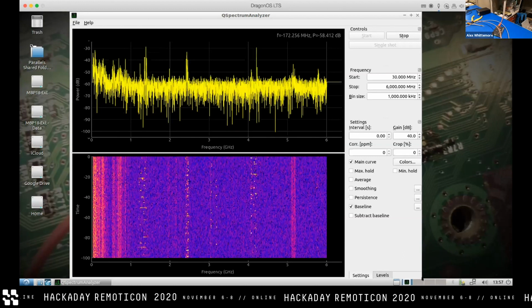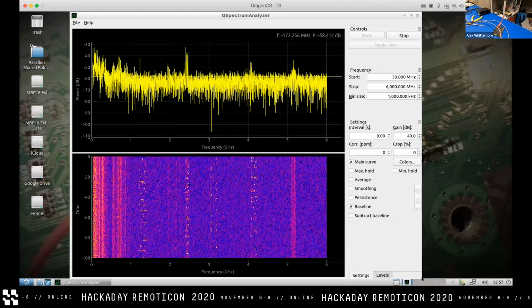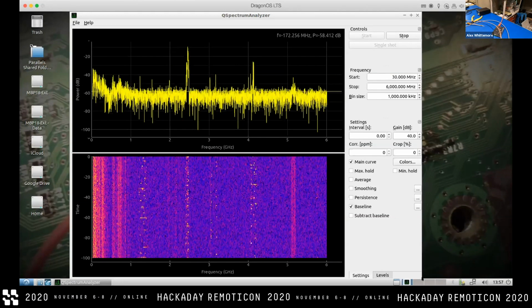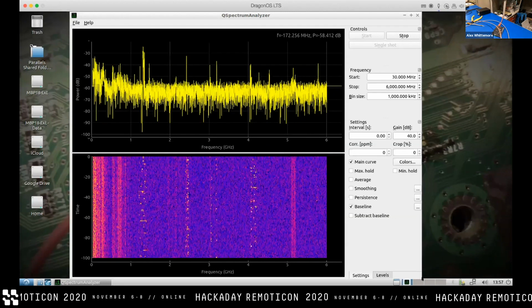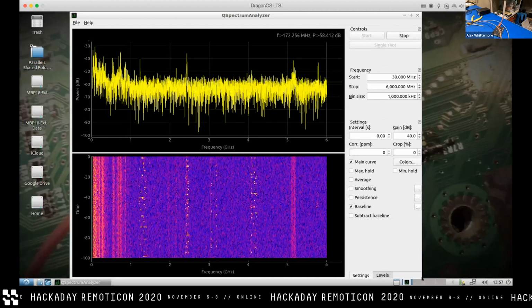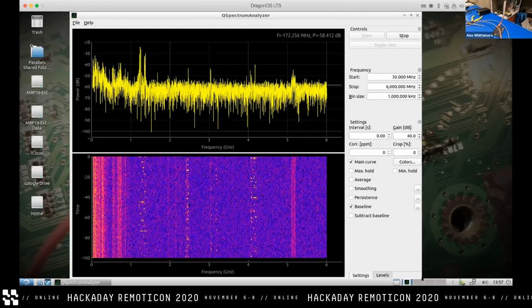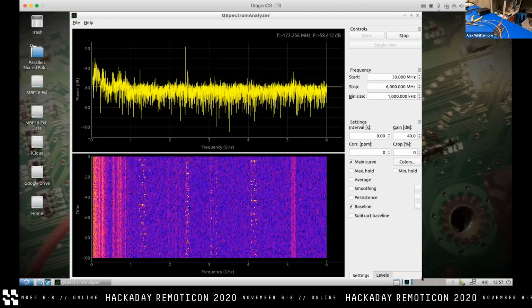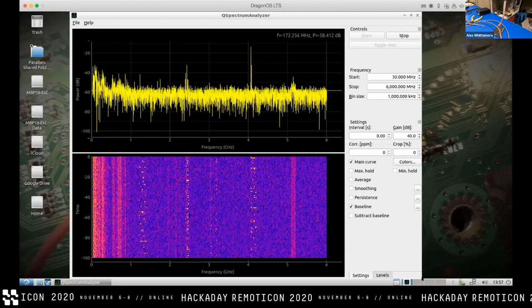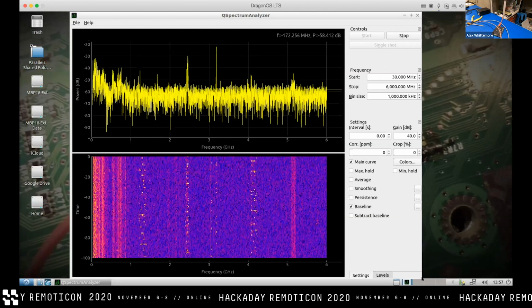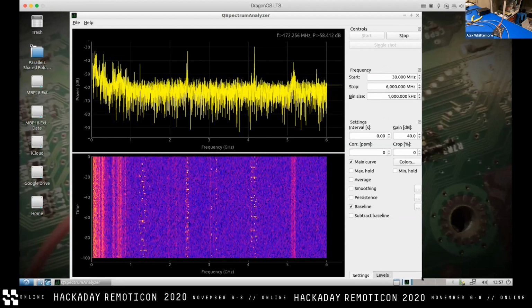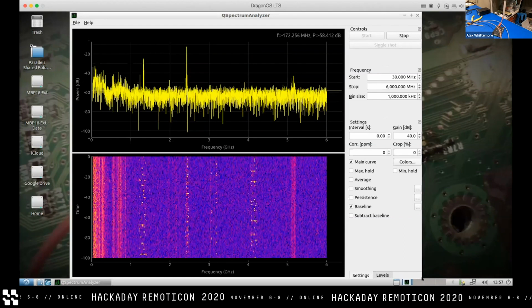So for background, for anyone else who might not be familiar, we've been covering radiated emissions primarily. Another seriously important aspect of emissions testing is conducted emissions, especially for stuff that plugs into a wall. So the question is, what kind of noise are we blasting out over the power supply into our device, back into the rest of the household or an office or whatever? The question is basically, have you tried building your own cheap hardware for doing those sorts of measurements, which, among other things, require a line impedance stabilization network and some other hardware?